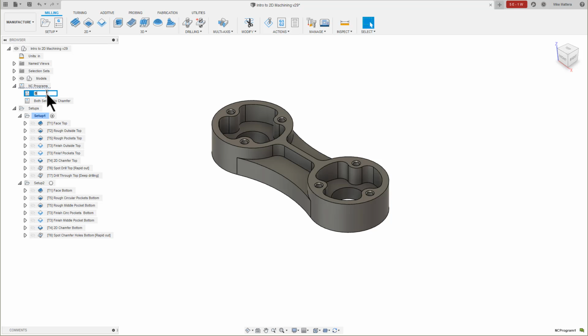You can create multiple NC program configurations to accommodate different output requirements. These might be for different NC machines with capabilities that would exclude certain operations. If your machine did not have rigid tapping capability, you could create an NC program operation that eliminates any tapping operations.